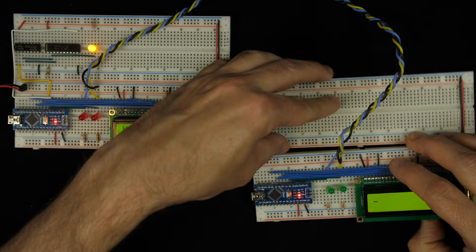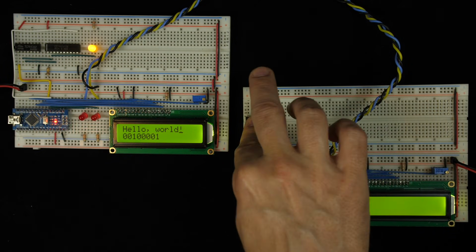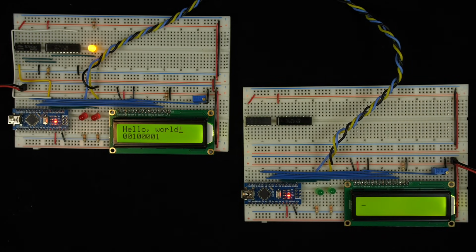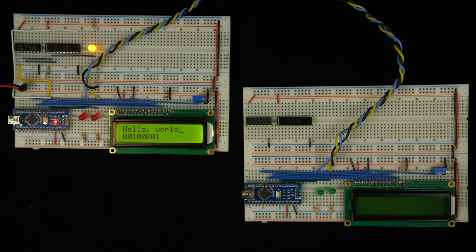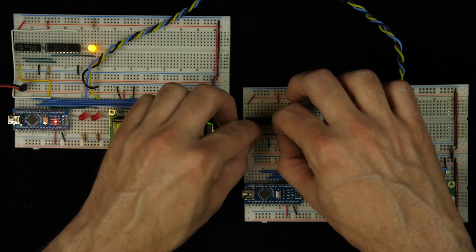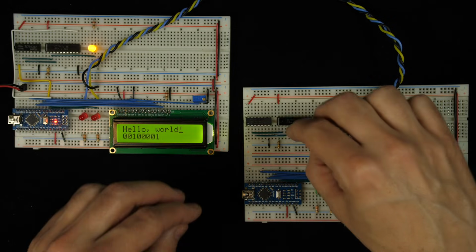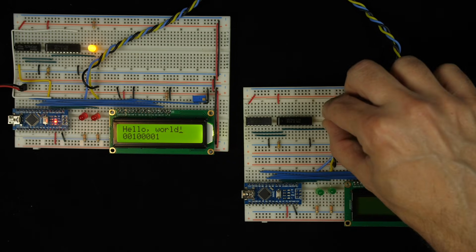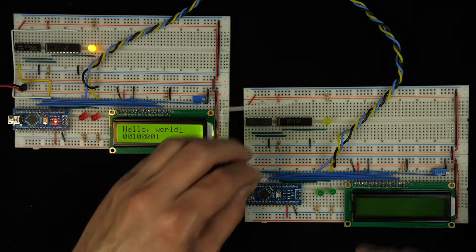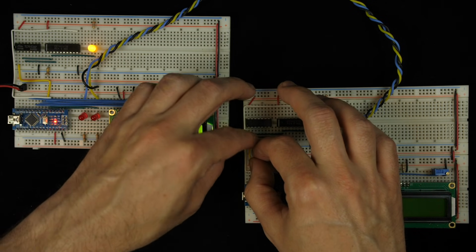So let's build the same circuit over here on the receiver side. And it's going to be identical. We've got a 74HC86 for the XOR gates and a 74HC273 for the D flip-flop. And I'll hook up power and ground to everything. And this time I won't forget to connect power between the breadboards. And I'll tie the reset line high through a 100K resistor. The output of the XOR gate will go to the input of the D flip-flop. And the output of the D flip-flop will go back to one of the inputs of the XOR gate. I'll also hook the output of the D flip-flop to an LED. And connect the other side of the LED to ground through a 270 ohm resistor. Then I'll hook the received clock to the clock input of the D flip-flop, and hook the received data up to the other input of the XOR gate.